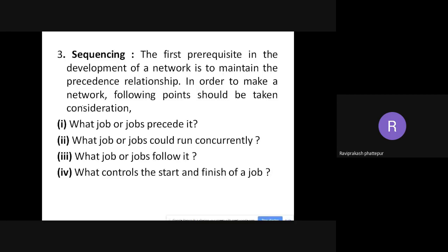For making the concrete, whether you get it ready mixed from outside or prepare it yourself, you cannot just put any amount of cement, any amount of sand, and any amount of stones. No, you cannot do that. There is a fixed proportion. They call it 1 is to 3 is to 5, or 1 is to 4 is to 6. So one part of cement, 3 parts of sand, and 5 parts of stones, something like this. I might be wrong, but it depends upon what you are doing.